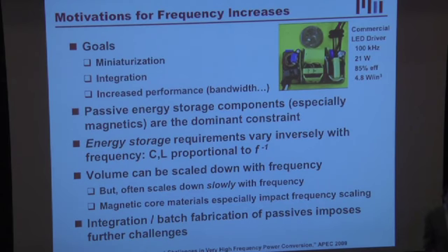But in particular, for example, how magnetic core materials behave greatly slows down how much size reduction I can get by going up in frequency. Moreover, if I want to integrate the components or batch fabricate elements in my system, that imposes additional constraints which may limit how quickly I can scale down in frequency. So that's a long way of saying that I may have to go up in frequency very far to get a relatively modest reduction in my overall system size.